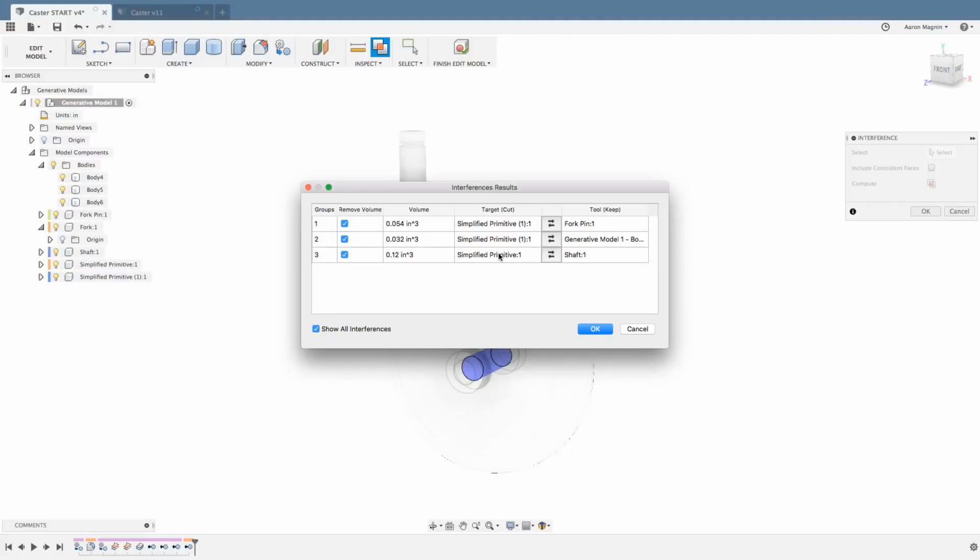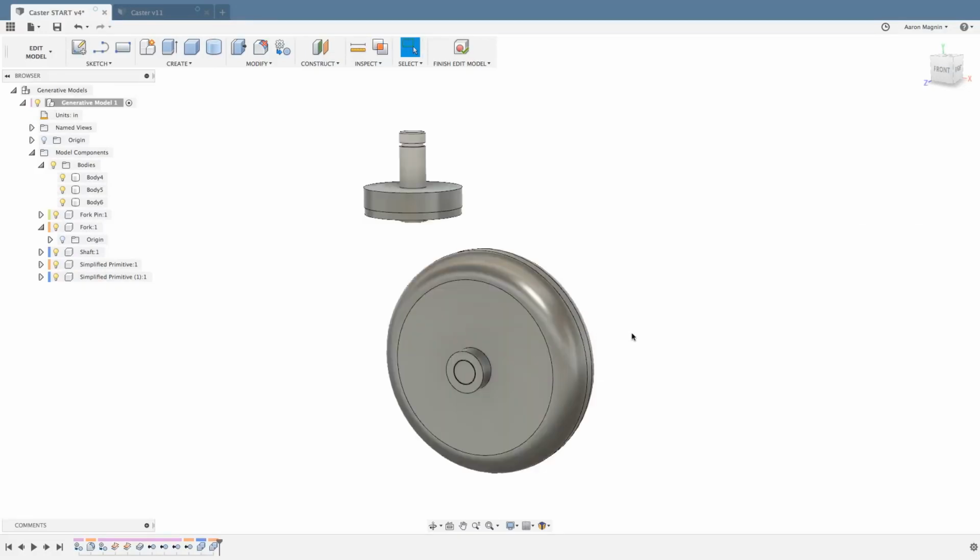It doesn't care where the shaft is. Even if the original part doesn't go in that area, these primitive replacement pieces are just that. They're real simple. So using this interference tool, we can very quickly cut, and this actually turned out very nicely. All the primitives are on the left-hand side, which is what I want. I want to keep any of the other pieces that we see on the right-hand side. So just like that, we can clear up any interferences. If we wanted to double check and verify this, we could do so. It even adds a feature when you do that, so you can see it actually does a combined cut essentially from that interference tool. So really handy. That is also in the Simplify workspace in the simulation side of Fusion 360.